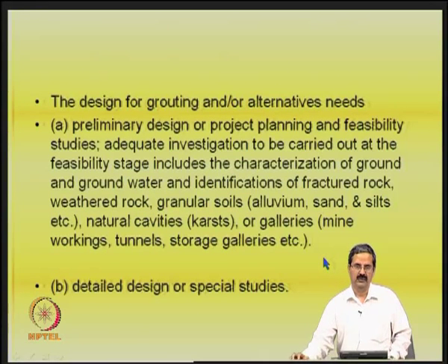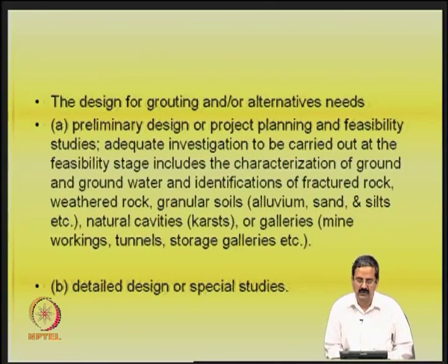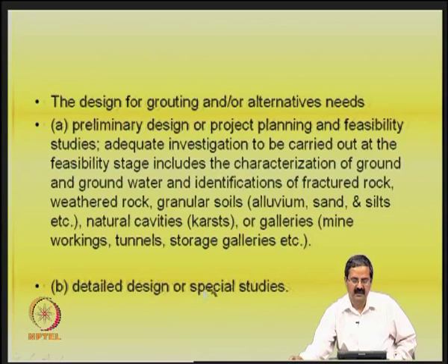Of course, one can do some testing, particularly in plain ground, like static cone penetration tests for improvement of bearing capacity. But one should be very careful, because it is a very complicated mechanism. Though the objective is simple, that it has to fill up voids and also increase the strength, the way it does so and the way it is going to be effective is something one should be very careful about.